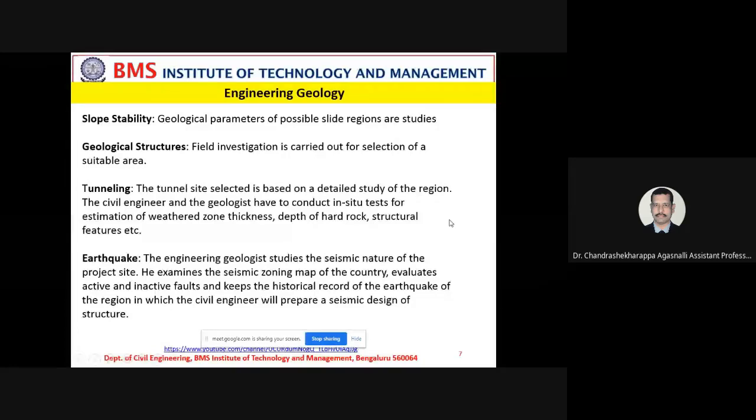In Madikeri and the Western Ghats, you can see why the landslides are happening there. That's because there may be a lot of fractured zones in the rocks, or highly weathered zones due to heavy rain. It's not going to tolerate the conditions, and it's going to erode. It happens. But why did it not happen before? For many years, this has not happened. That's a question mark.